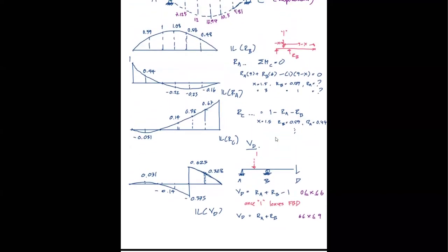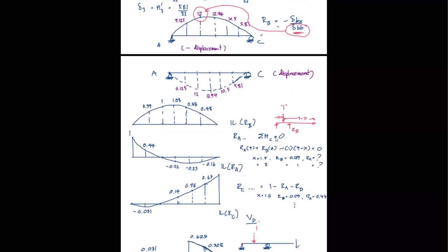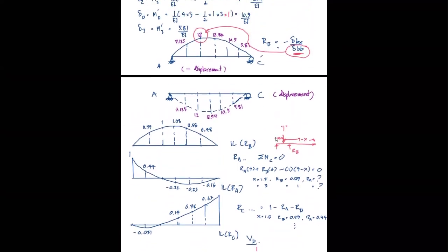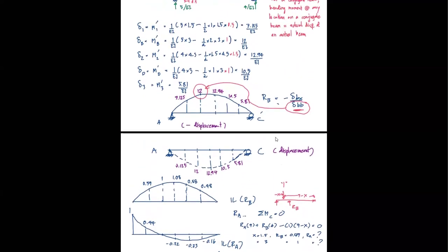See, the whole fundamental key to this is how to turn the information here, which is the displacement, into the first influence line. So the most important thing is just to know how to turn the displacement that we calculate here into the influence line of the first reaction.